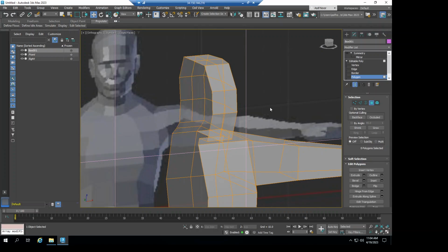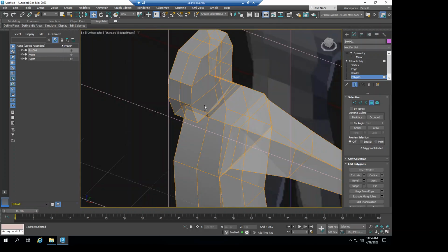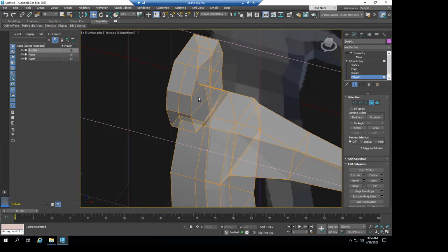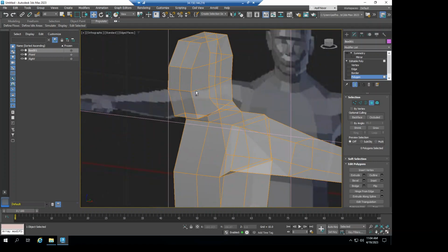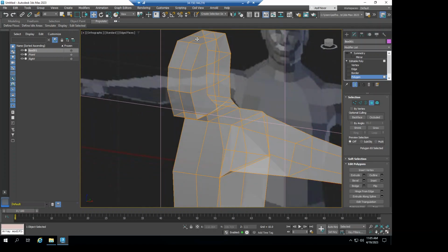Yeah. So you can rotate this around. See, not very realistic looking, but still we have a shape. And then now we select this. We go back to the edge selection or maybe vertex selection, and then select this top vertex here. Go to the front.